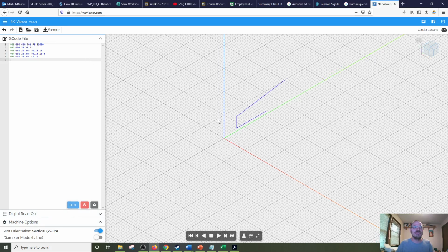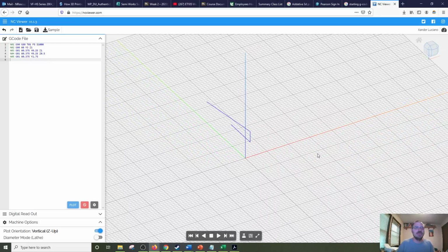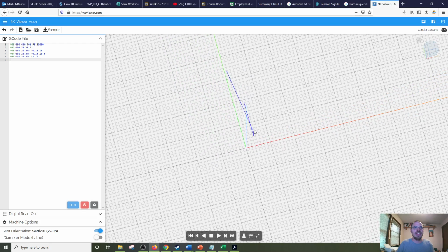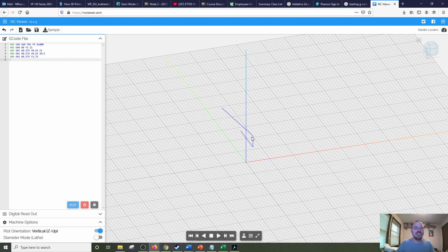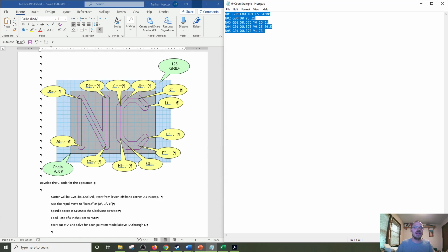We're going to plot that. So if you notice, we were up here to begin with, and we're moving down above where we wanted to start the N, moved down into the first portion of the N, and then moved up to point B, right? So if you finish this, you should see an N, a lift up, go over to the C, and then around the C. So that's a good way to check to see if your G code's working correctly. And I'll post a link to one of those G code testing sites. It's literally the first thing that comes up on a Google search.